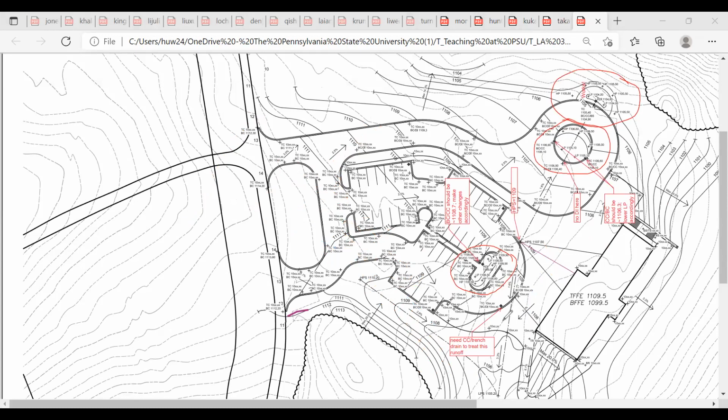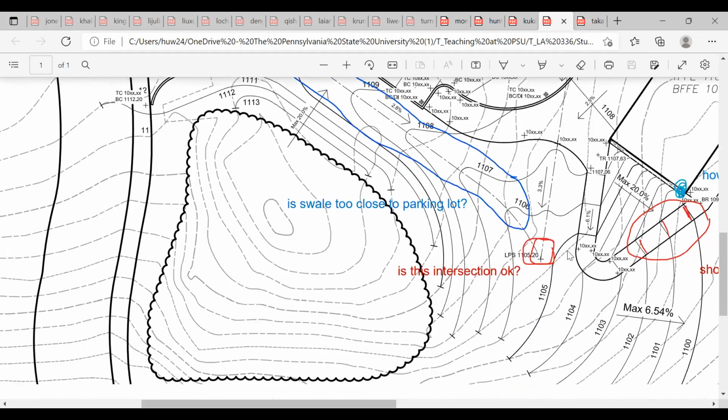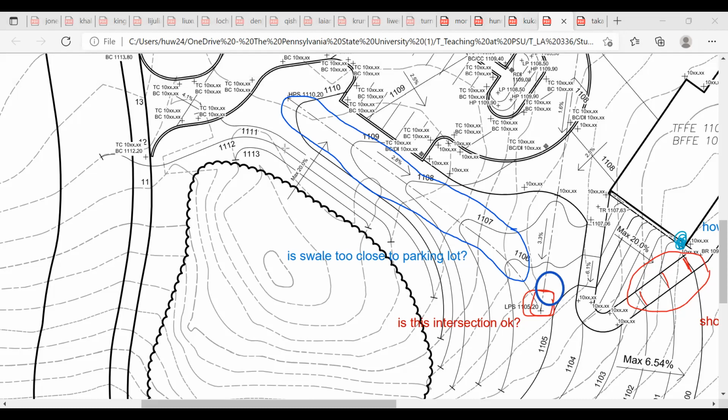Yes, so I did not mark the specific location, but I did say, yes, you need a trench drain over here. Let's go back to this assignment over here. It looks like you have room in this area for that one. Oh, I actually would recommend doing it right here. Move it up. So that's your retention for your plaza.